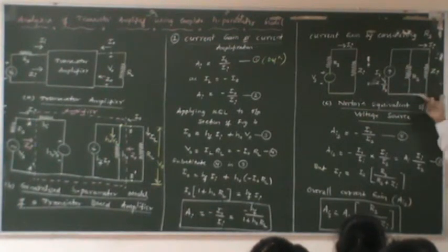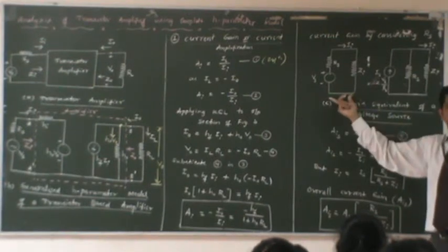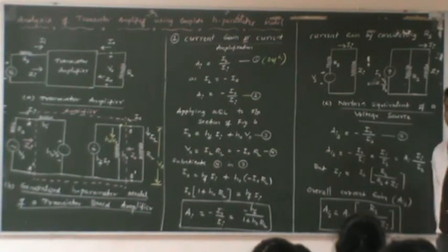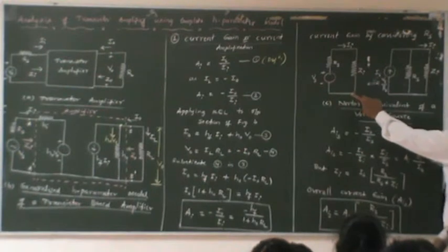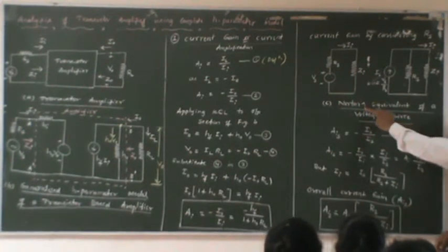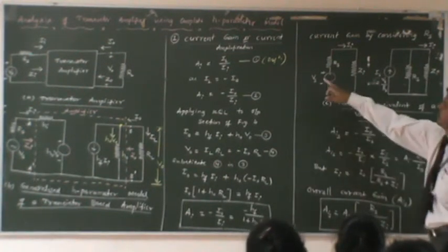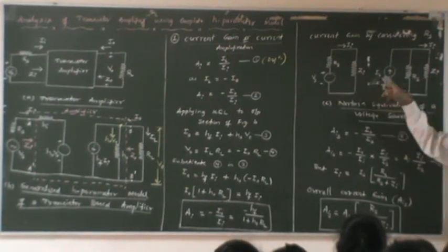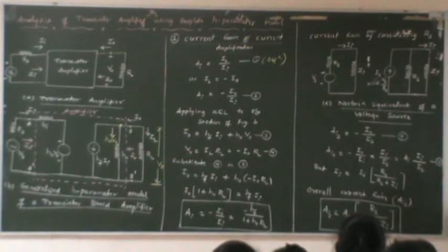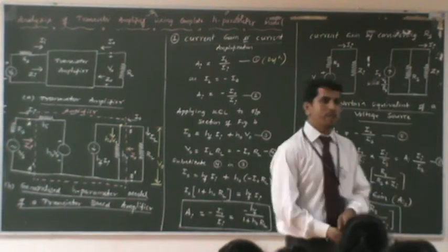Have all of you understood this change here, how we have obtained this circuit from the original input section? This has been extracted. Here, what we have done is calculate the Norton equivalent circuit by converting the voltage source and resistance into a current source in parallel with the resistance. The rest is simplification. Let's go as per the definition.